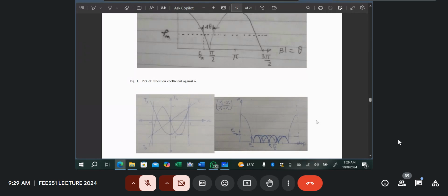You can also give another example in the passband characteristic for 2-section Chebyshev, which I think is in the notes here. Again, design a passband characteristic for a two-section one, the one that was given to them. You show us the formula, especially in the case where you've been given rho M. You are told not to go beyond this threshold, 0.05. So how do you find it? You're given the ratios of the impedances. How do you get there? How do you calculate the fractional bandwidth? And then show us that plot that we are seeing here.